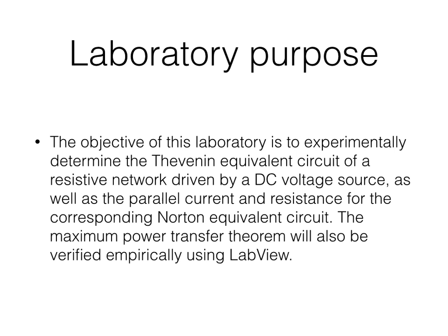Now we are moving on to the main part of the lab. The objective of this laboratory is to experimentally determine the Thevenin equivalent circuit of a resistive network driven by a DC voltage source, as well as the parallel current and resistance for the corresponding Norton equivalent circuit. The maximum power transfer theorem will also be verified empirically using LabView.